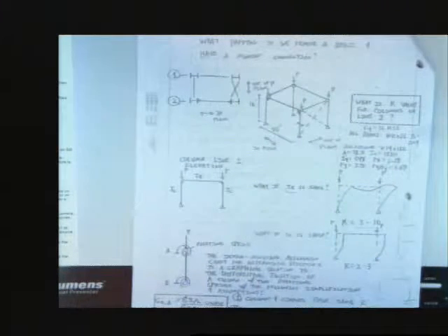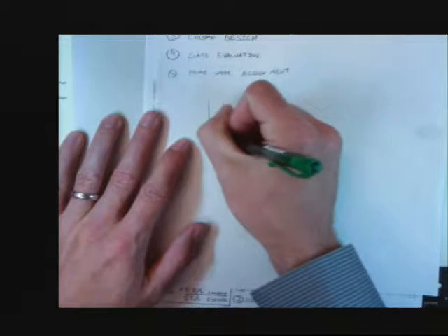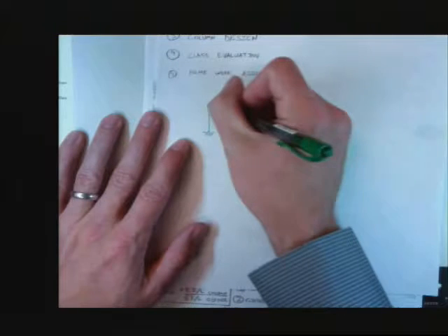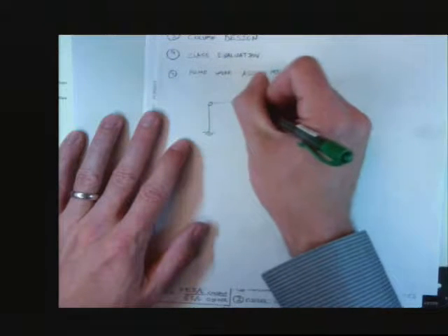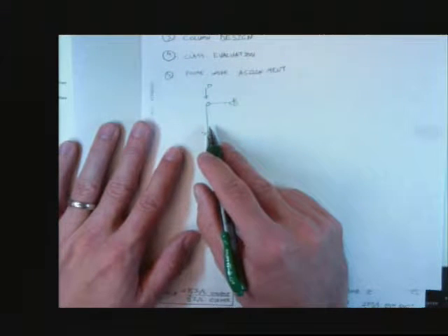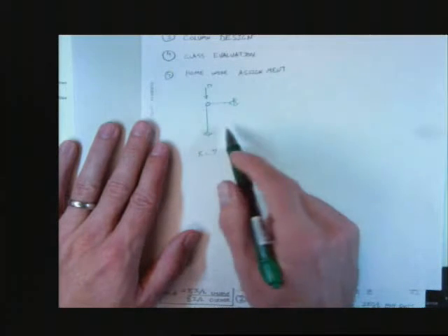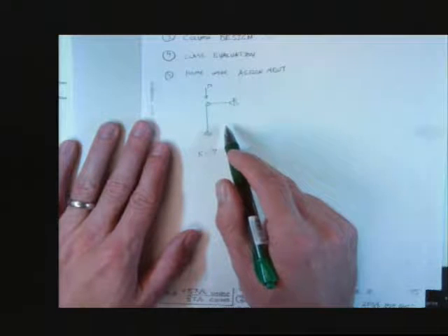Okay, we were talking last time, and we'd gotten to this page in the notes. We'd gotten to these situations. We'd previously been talking about situations where I have a girder that looks something like it's fixed at the bottom and it's got a pin at the top, it's got a load P. What's the K for that? 0.7. Is it sway or no sway? No sway, right?